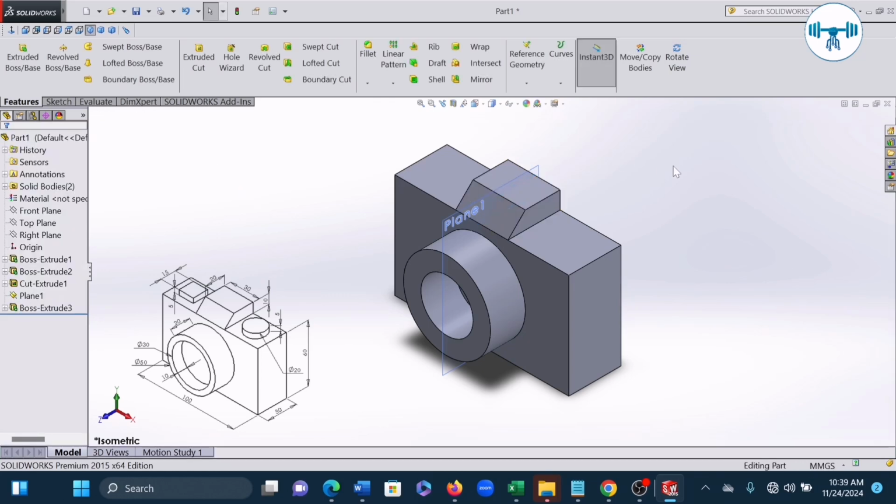Okay, can you see what we have? So can you see what we have? Exactly, this is perfect. So nobody will know that we used 2 directions of extrude to do it because we merged it. That's what merging does. So we have 2 more features to finish up this drawing. We have the box by the extreme end, and then we have the small cylinder too by this end, I guess representing the buttons of the camera.